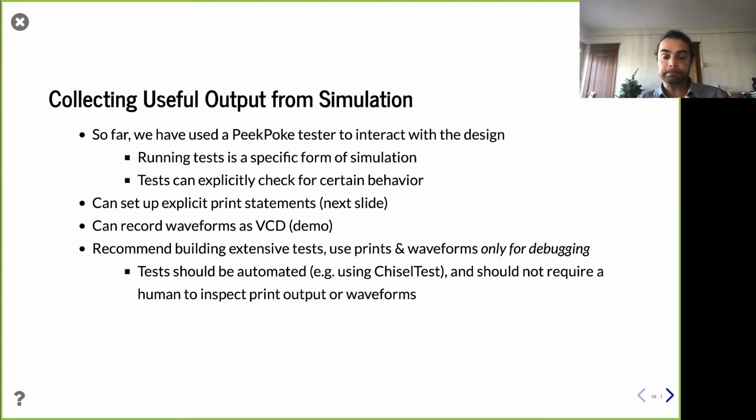They're good. Both prints and waveforms, I think, are really helpful, but I haven't emphasized on the slide, only for debugging, right? I think it's very common for people to try to use them for testing too. Like, oh, if the output on this line of my code is 4, I know I got it right. If it's not 4, I know I didn't get it right. Don't do that, right? Because then nobody else can use your test. You want your test to be automated. You want to have pass, fail. You want to see that coming out the other end.